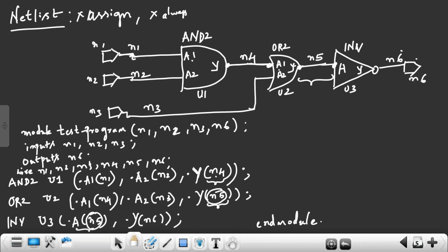Gate level netlist. In a gate level netlist, you have what cells you have used from the library to form your design, and what is the connection between the cells. That is present in the gate level netlist. Apart from that, you should not have any keywords like assign statements, always block, non-blocking statements, blocking statements, what you see in Verilog, right? Nothing should be present in your netlist.